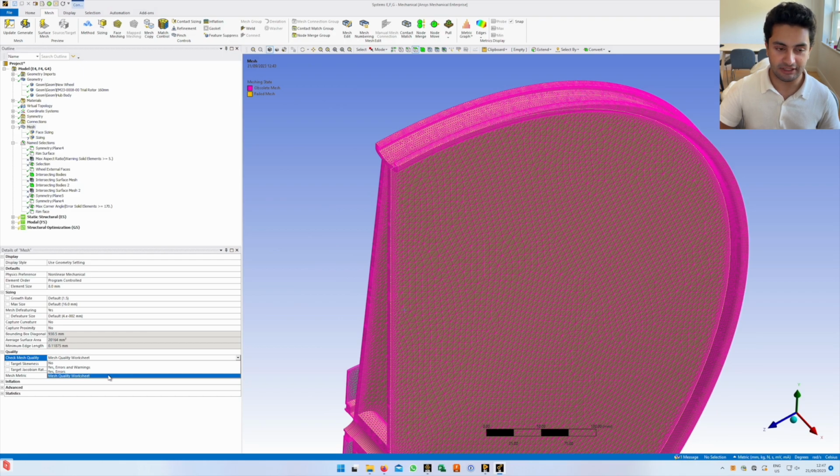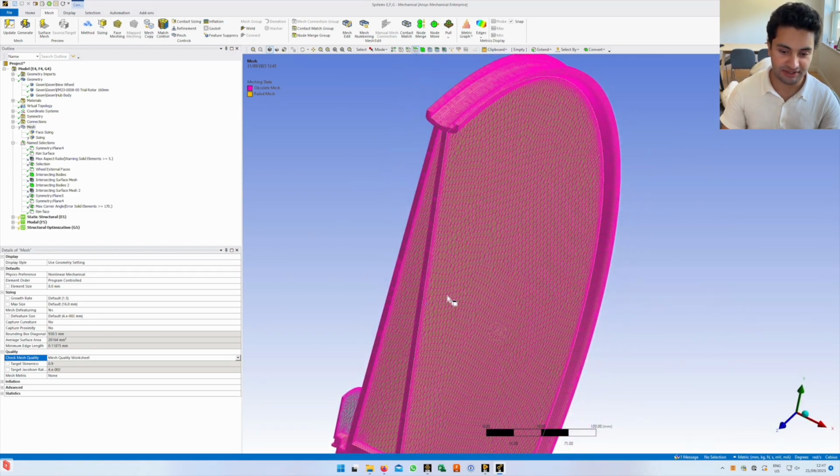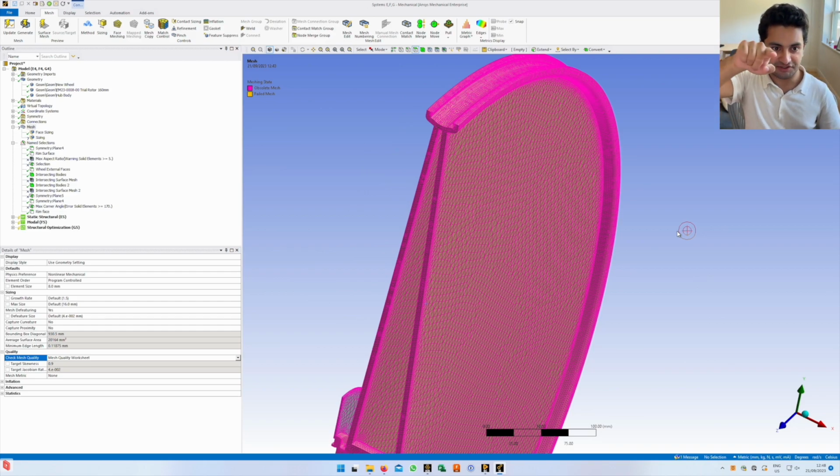We'll perform a simulation, gather some results, so perhaps a graph of deformation of the body through a specific coordinate. And you'll get a plot of how that deformation is measured. On the x-axis, you've got your number of elements, on the y-axis, you'll have deformation, and then you'll get a curve, and eventually that curve will plateau at a certain number of elements.